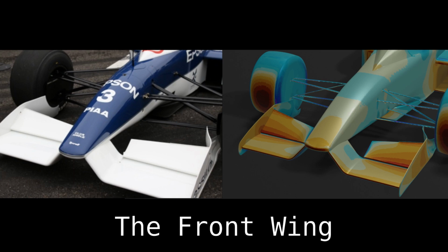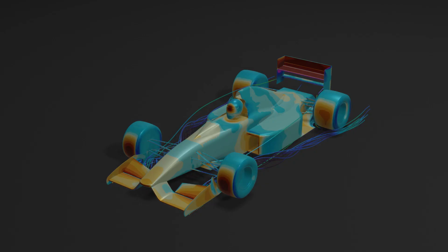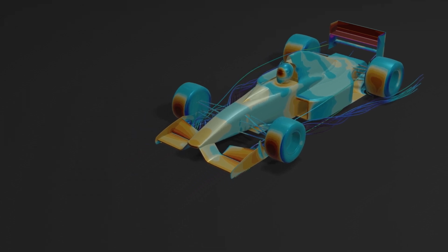Its purpose was presented in a previous video, and it was concluded that it was a device for downstream effect. However, it didn't have a well-functioning profile, and had flow separation which I didn't attempt to fix. I fix it here, but it also has a small downstream effect. The issue with the dihedral wing is that the main profile seems to be compromised due to having a very inefficient structure. That is, most of the span is in bending moments. Therefore, it is rather thick compared to other wings of this age.